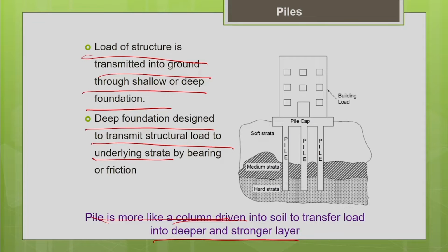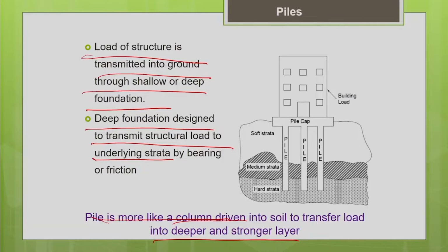So, when do we go for a pile foundation? Basically, when we have weak soils or soil with poor bearing capacity, we need to transfer the load till we reach a depth where we can find a hard load bearing strata. Till that depth we need to transfer the load, and for that we need a deep foundation like a pile. The other requirement may be if the design load is very huge. Say, for example, you need to design a foundation for a skyscraper or a multi-story building, where the design load is very huge. In that case, people commonly go for the pile foundation.